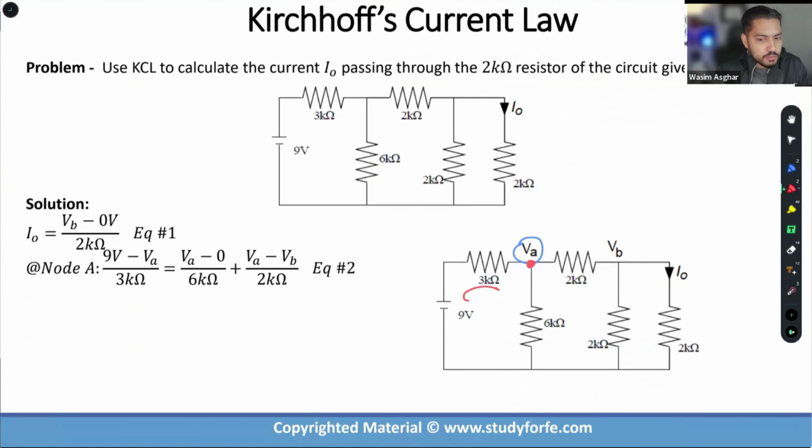So we've assumed that this current is entering, this is leaving, and this is leaving. Pretty simple, straightforward. Always throw a virtual ground, right? Now using Ohm's law, assuming that this is the direction for the current flow from 9 volt to 1, the higher voltage is 9 volt, right? And remember that sum of current in has to be equal to sum of current out, correct?